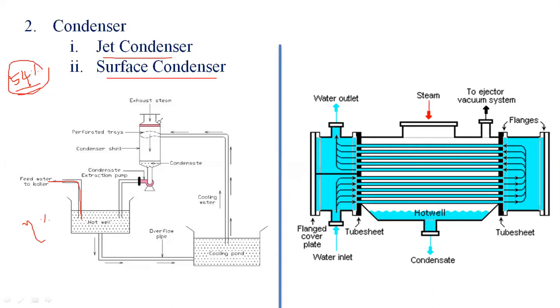In that, how much is the efficiency of the boiler? Almost, in that, 60% of the steam is there. Suppose the boiler output is 400 degrees centigrade. This 400 degrees centigrade we are reheating in the superheater, and the temperature comes to 420 degrees centigrade. This drives the steam turbine. The steam ejected from the turbine drops to about 360 degrees centigrade. Again, we are reheating. The surface condenser is the one most preferred in thermal power plants.